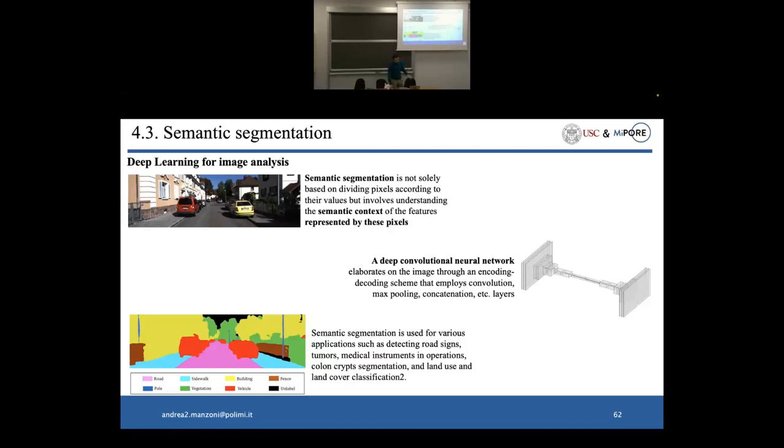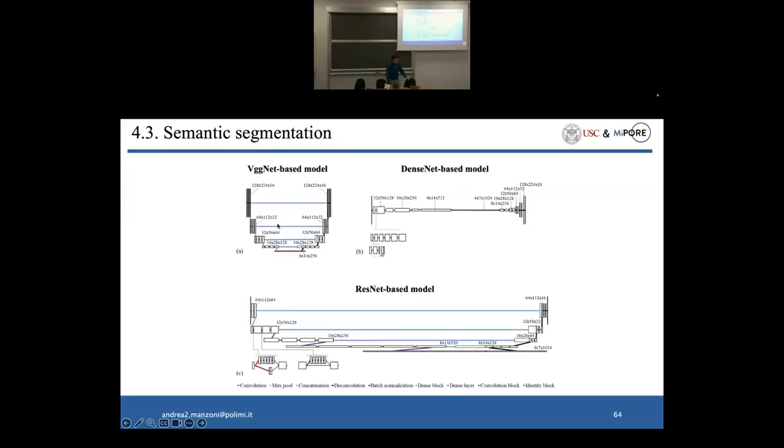After that, our question was, we are able to estimate the early arrival time and preferential flow path in a regular manner, as done before, using flow and transport simulation. But is it possible to estimate the preferential flow path position without solving for transport, using a deep learning technique? So what we have done is use a convolutional neural network, of the kind usually used for semantic segmentation in autonomous driving to divide the street from cars from trees. We have used it to divide areas where we have the preferential flow path from areas where we don't, within an image that represents the hydraulic conductivity field.